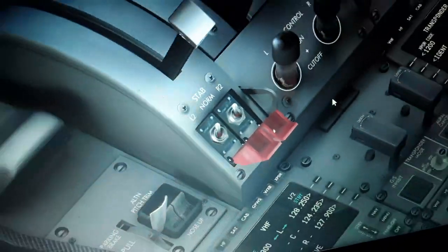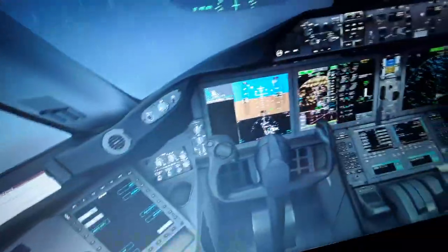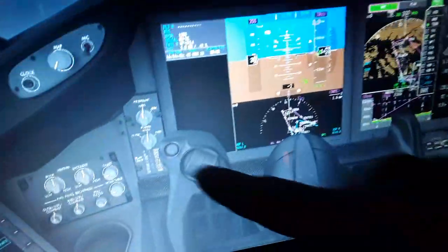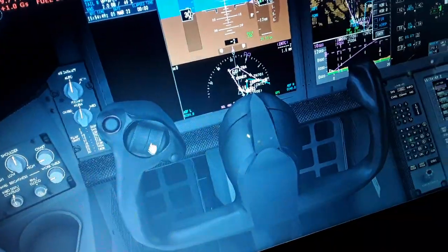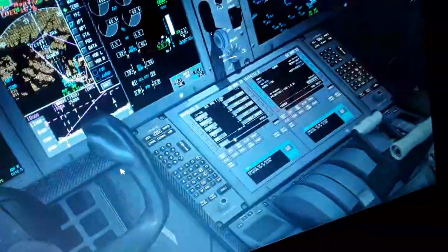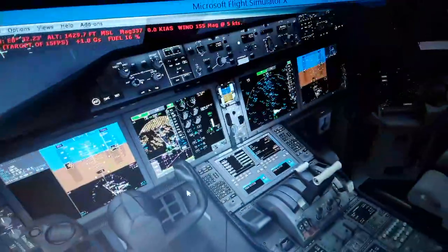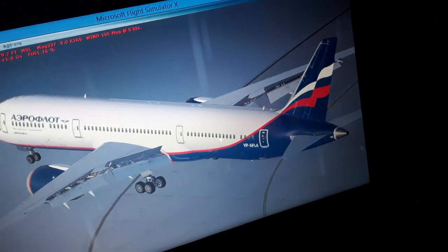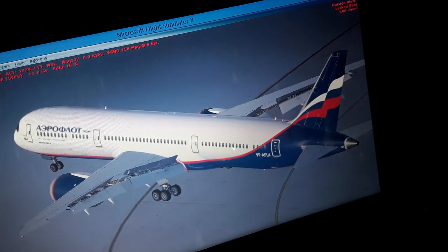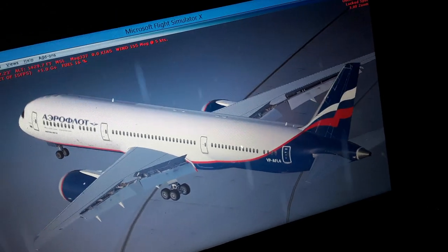Disconnect this from normal to cut off, and use only the horizontal trim stabilizer over here, the manual input. So you will be flying in direct mode, I believe. Since this is a fly-by-wire aircraft, it has the normal mode with the auto trim and the protections, and a direct mode if you have a failure of the hydraulics.